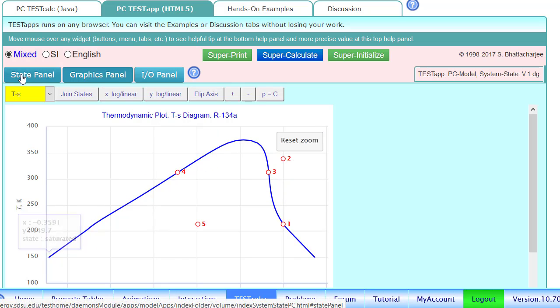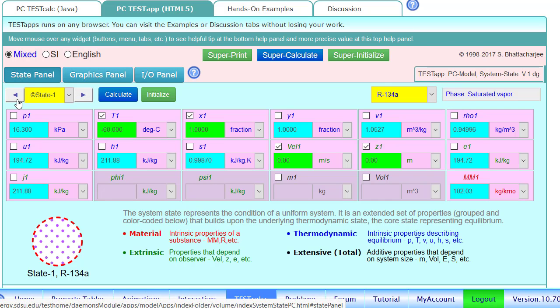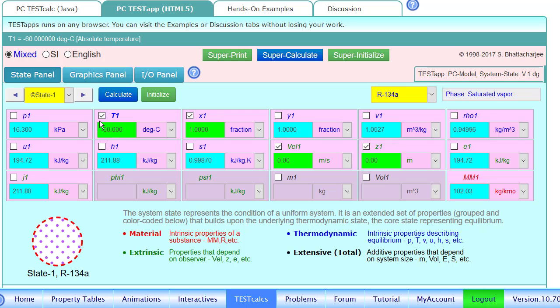So a good point to also bring up is that if there was like a what if scenario question and it said that actually state 1 is going to be negative 50 degrees Celsius. Well, that's why in all of these problems, instead of entering the exact values of S2, like 0.9987, we enter equals S1.